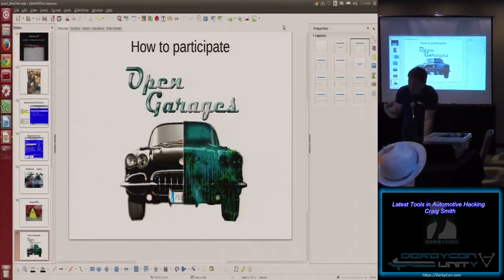On the dealership tool side or the password tool side, it will go through and calculate what the number should be. It passes it back to the ECU, and the ECU says, all right, cool, now I'm willing to take changes. So with this tool, what you could do if you wanted to is spoof the request, so the initial seed part, to try and get your dealership tool to give you a bunch of valid keys, assuming you have it.